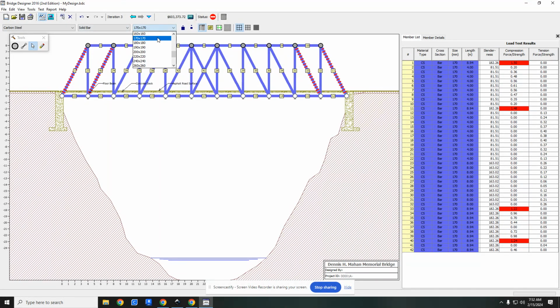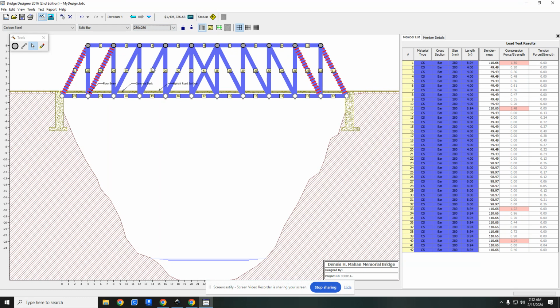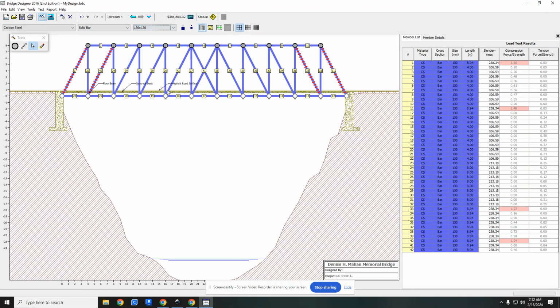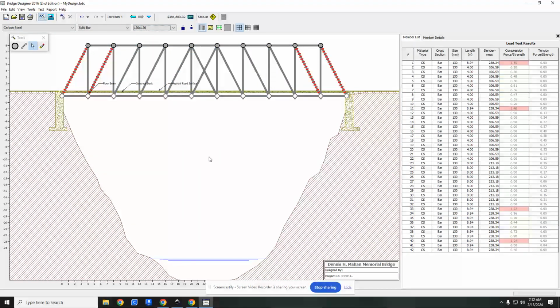And the easy way to do that is obviously just make the beams thicker, but I want you to play around with the thickness of the bridge and then really focus on the structure. If it fails at first, try playing around with some different geometry and see if that gets you a better result. Because if you can improve your geometry, you can end up using thinner beams and get a lower cost bridge. Right? So that's the basics on how to use this software. Go and experiment.